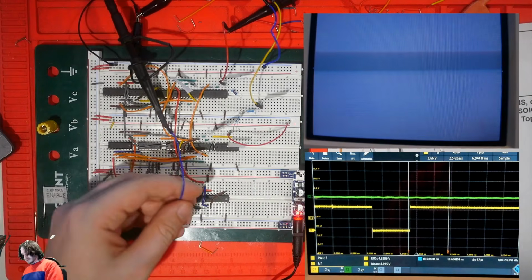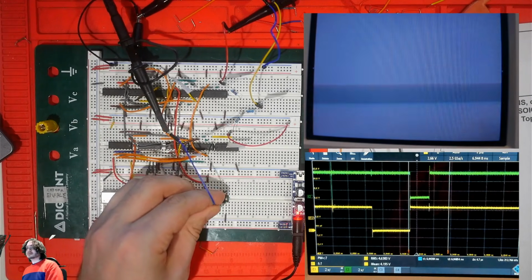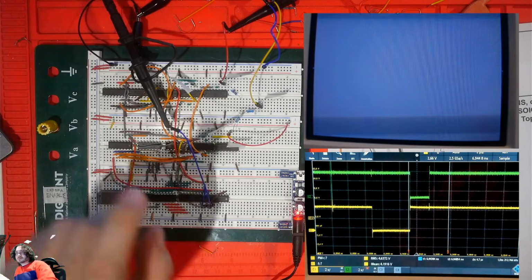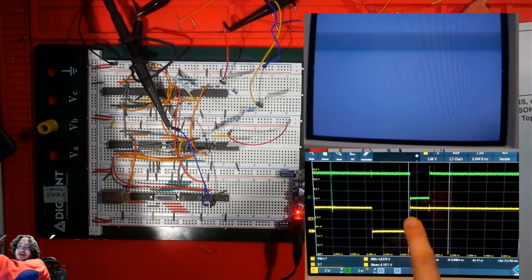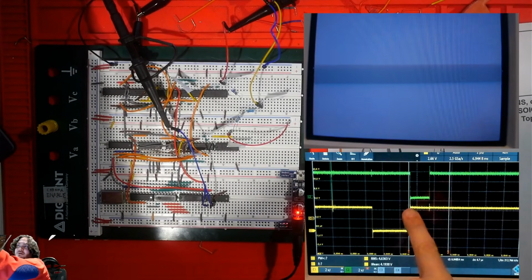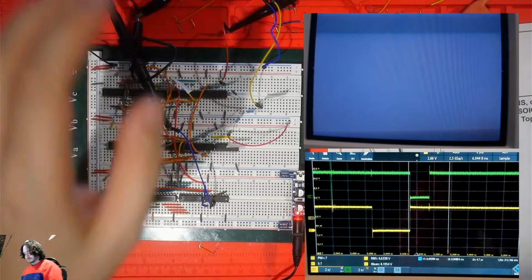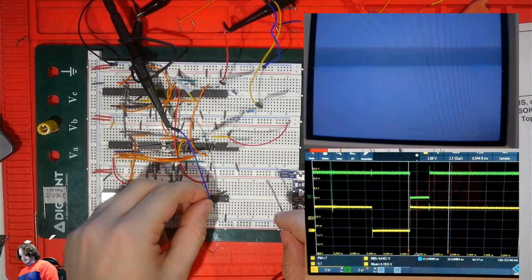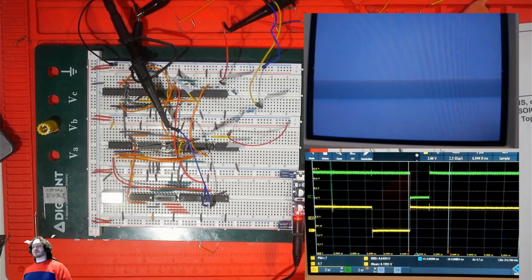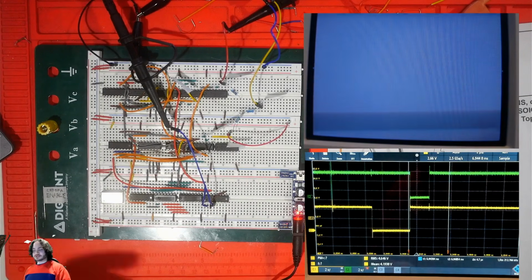Because an AND gate actually can be used sort of as a negative OR. So the negative time we want to have combined. So we want it to be low here, but we also want it to be low here during image enable. And when you have an AND gate, if either one is low, then the output is low.